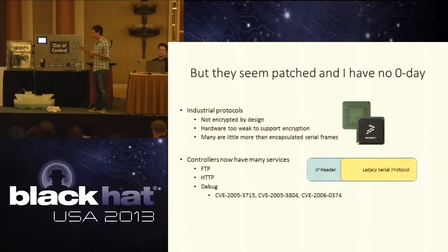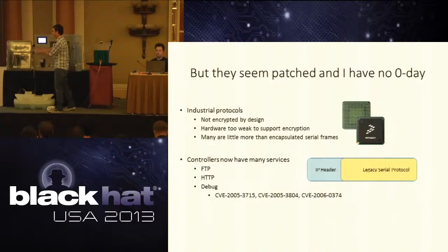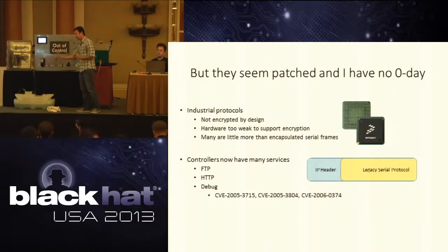Okay, so there are a couple of different things that we can do with the controller. One is binary exploitation, traditional buffer overflows and stuff like that, because a lot of these guys don't have the protections that you would see in a normal Windows machine, such as DEP and ASLR. These are just really old, simple machines. But what we want to do is go after the protocol itself. We want to build a packet to tell the controller to drive its I/O without actually modifying the logic, just telling the logic to essentially be quiet and drive those signals ourselves.